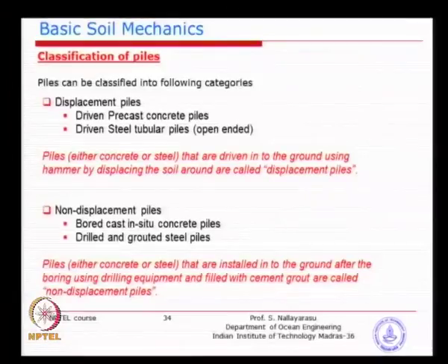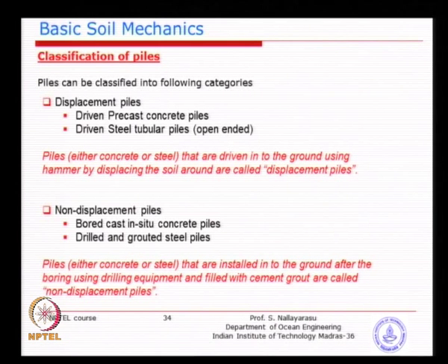So, basically what is the difference between the displacement pile and non displacement piles? One of them is creating better characteristics of soil, the other one may degrade it. During the process of drilling, you are disturbing the soil, you remold the soil. So, it may take several months and years to get back its original quality and characteristics. But depending on the situation we apply each one of them.